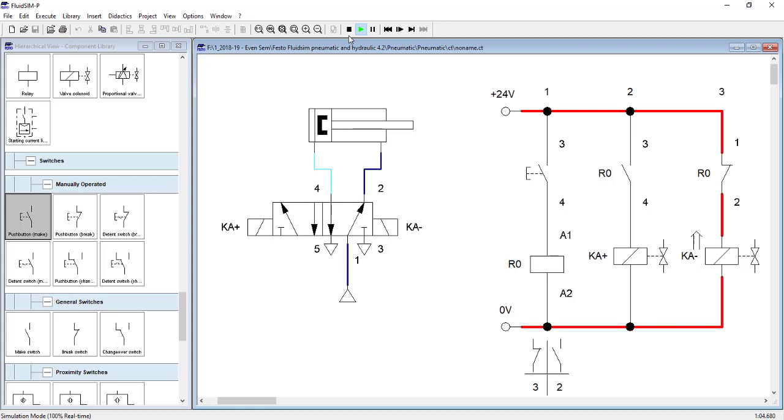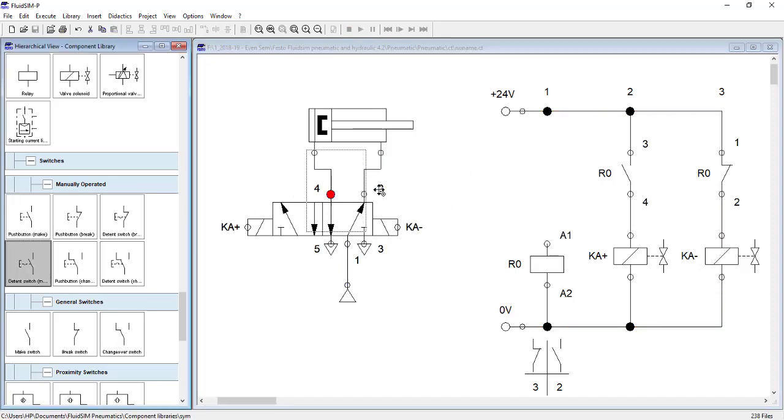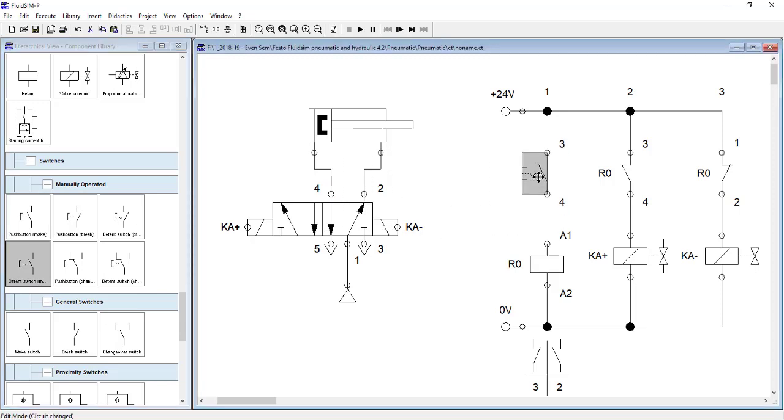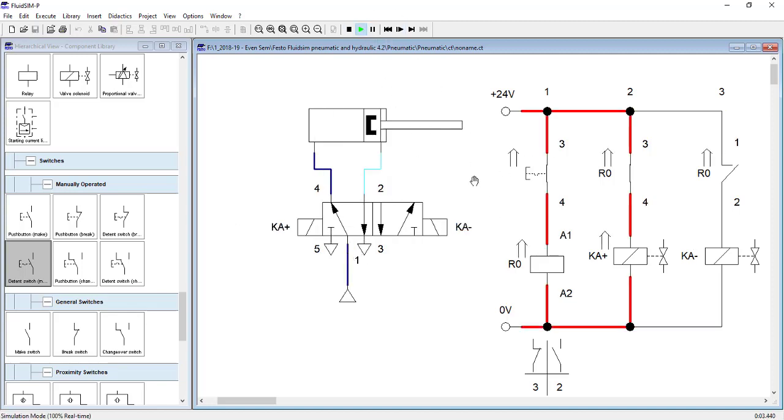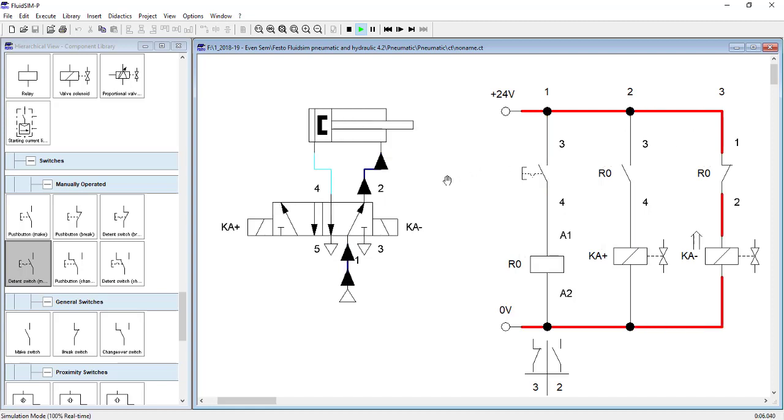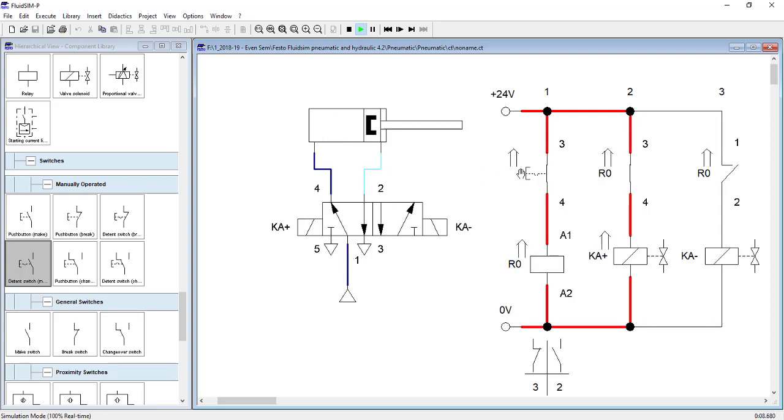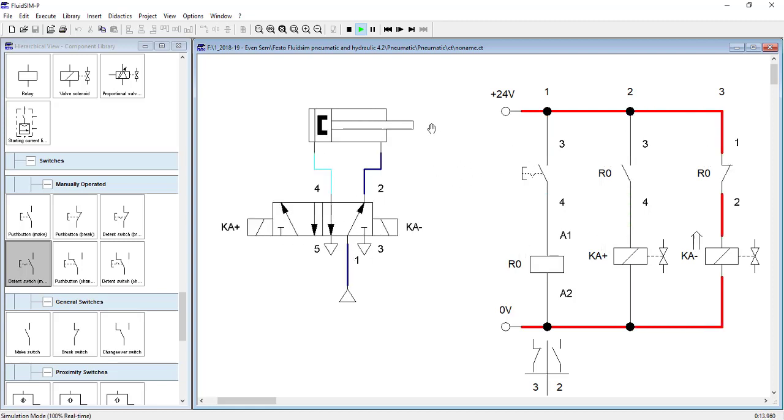Right? So rather than keeping a push button, what can I do over here? I can put a switch so that when I push the switch, the piston comes out and stays out. When I want the piston to go back, I will again press the switch so that the piston goes backwards. So on, I press the switch, the piston has come out, and now when I press the switch again, the piston goes back. So in this way, I can control when the piston comes forward, when the piston goes backwards. Right? So this is a simple circuit to control the operation of a piston.